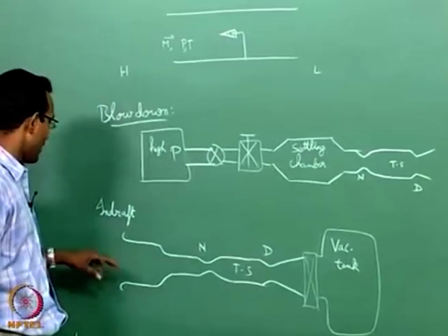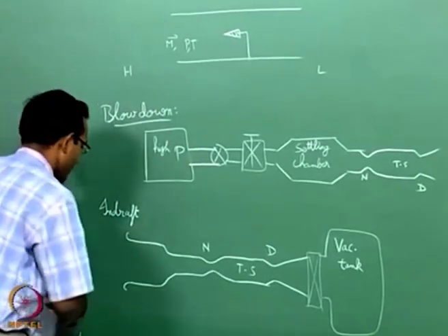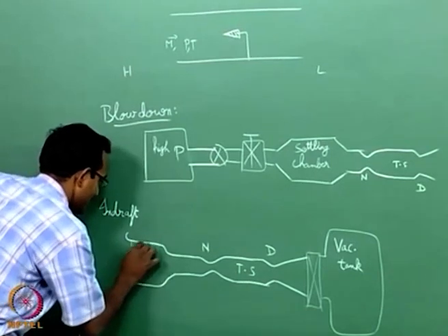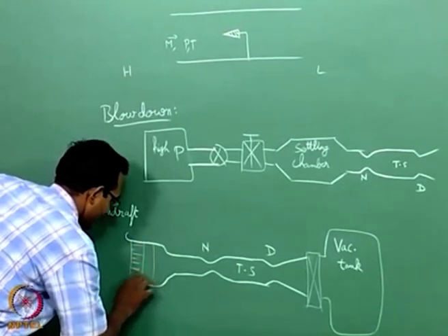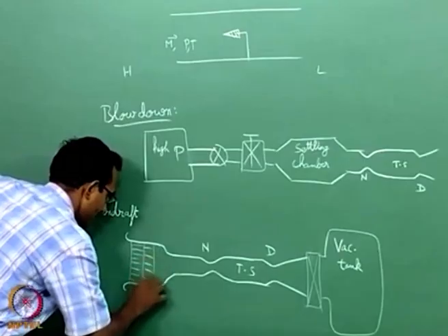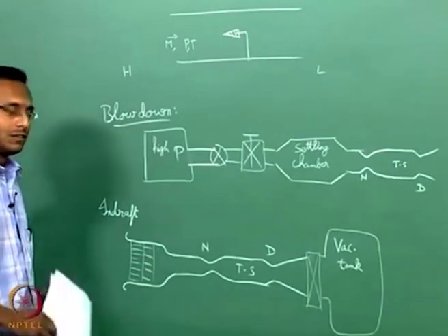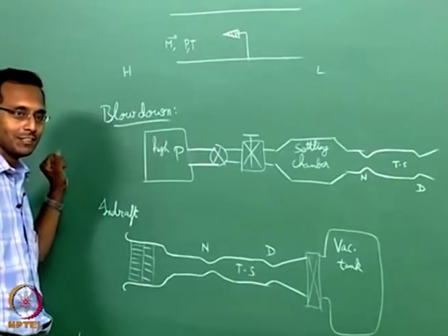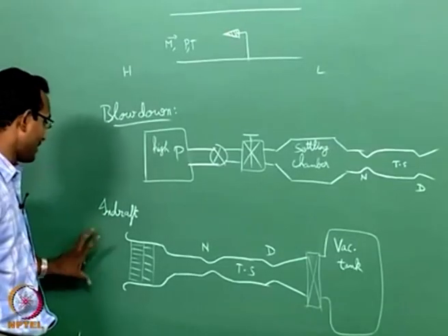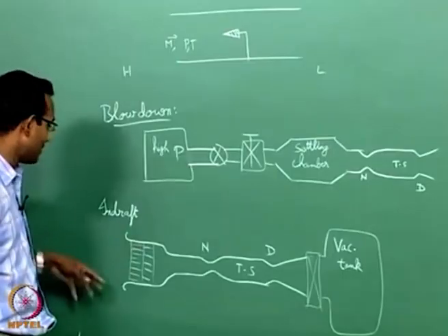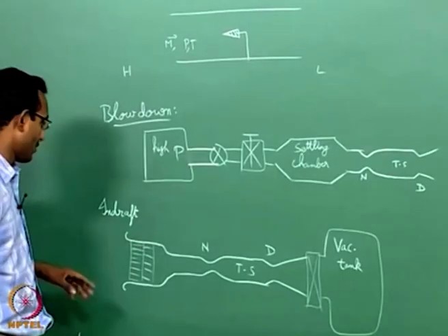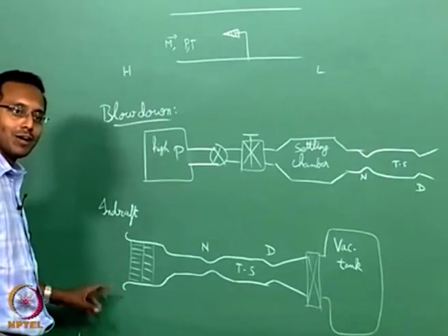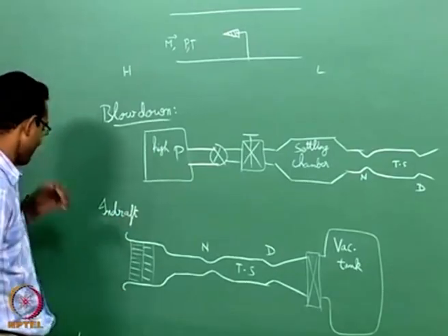Anyways, the way I am doing it here, I am going to say atmospheric pressure here, and I am going to have some grids to decrease turbulence. Okay. You would have seen such things in fluid mechanics when we were discussing low speed tunnels. Typically they have this kind of intakes to decrease disturbances outside. And they will have this kind of very nice intake to have better intake efficiency.